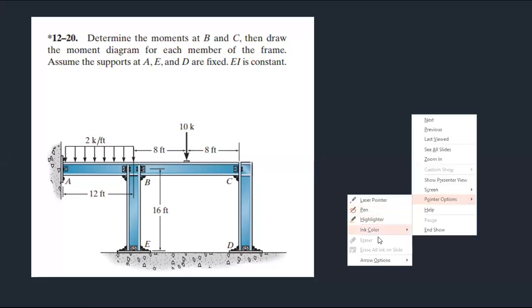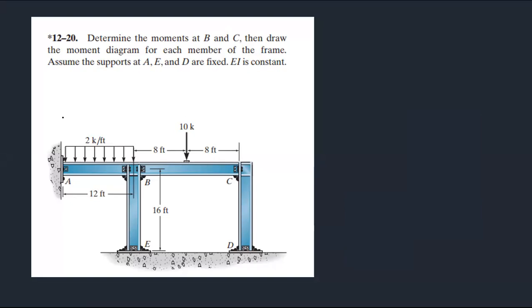First we need to determine whether the joints are fixed, continuous, or discontinuous, right? We know fixed is going to be fixed. This is very simple, and there are three members. That means three bending moments at the joint, right? In the first or second video, I showed you if there are two or many members, sigma M should be 0, right? So that means it's a continuous one.